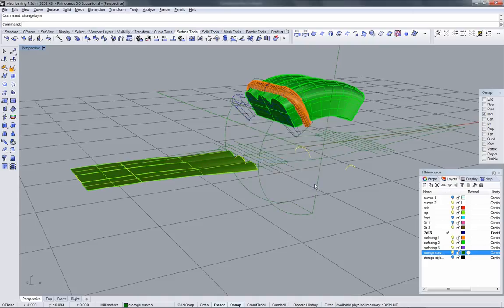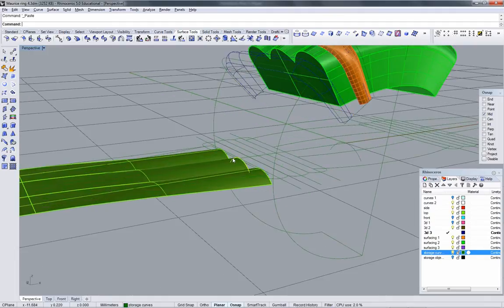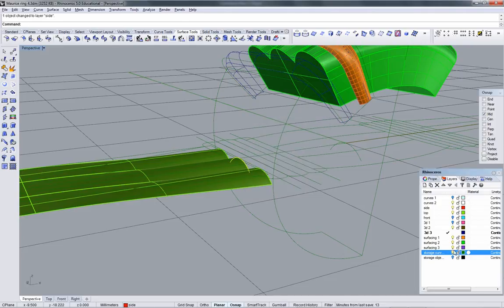Actually, what I'm going to do is Control-Shift-G. I'm going to ungroup them. I'm going to select this one. Control-C, copy it to clipboard. That goes outside of Rhino. So now I can undo my ungroup and then paste, Control-V. So now I have my original group and this separate curve. I'll only take this separate curve out of storage and put it on my red layer.